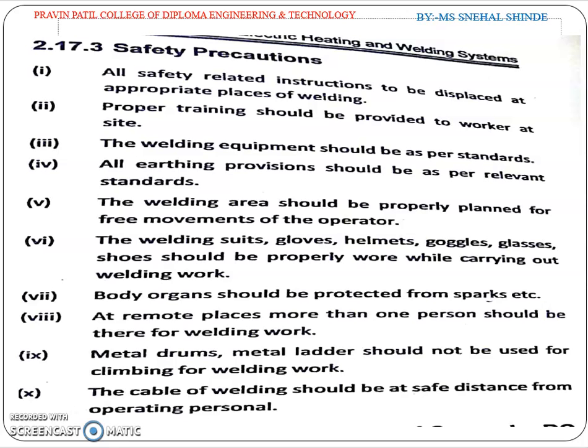The welding area should be properly planned for the free movements of the operator. So the operator can move freely. The welding suits, gloves, helmets, goggles, glasses, and shoes should be properly worn while carrying on the welding work.